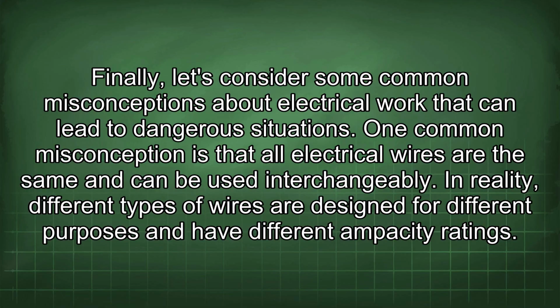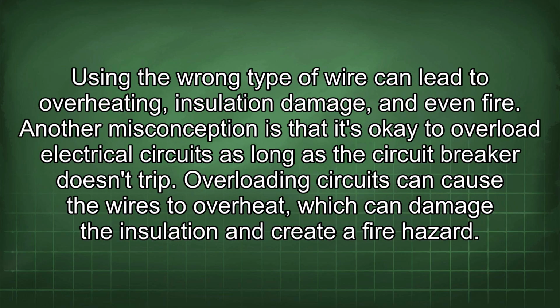Finally, let's consider some common misconceptions about electrical work that can lead to dangerous situations. One common misconception is that all electrical wires are the same and can be used interchangeably. In reality, different types of wires are designed for different purposes and have different ampacity ratings. Using the wrong type of wire can lead to overheating, insulation damage, and even fire.